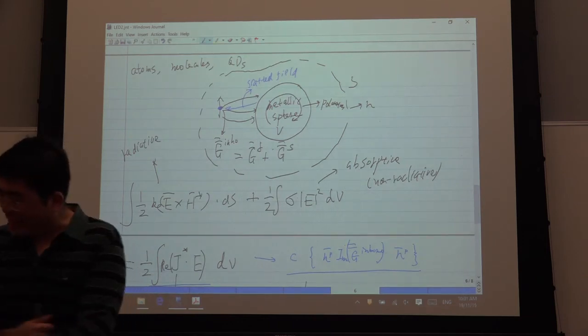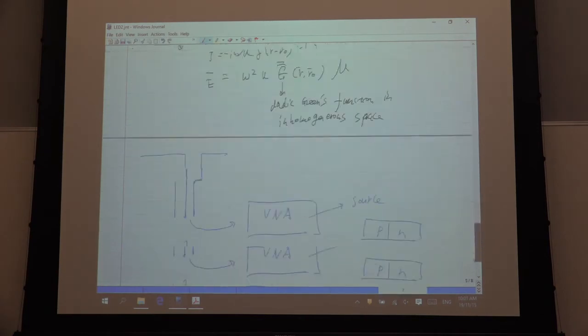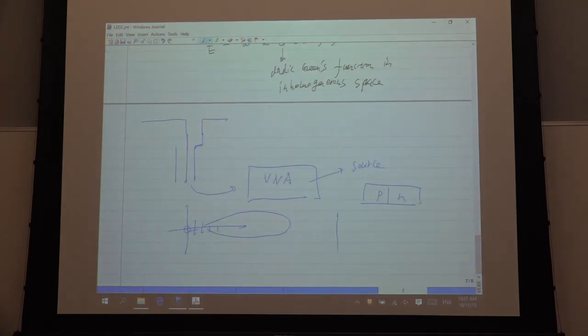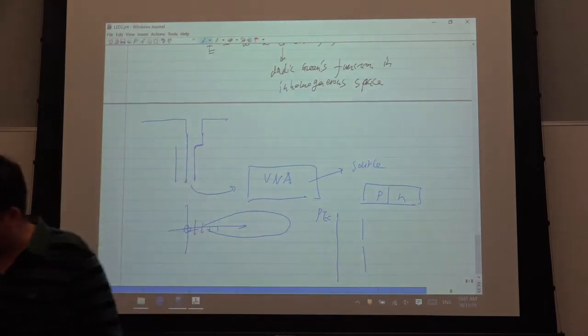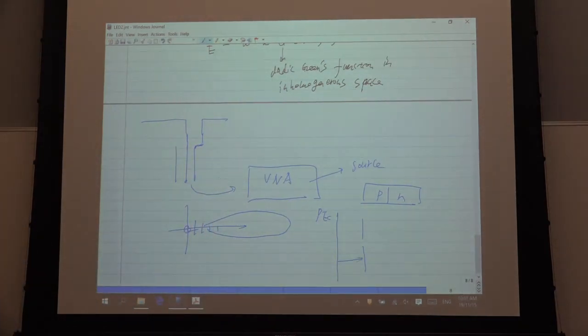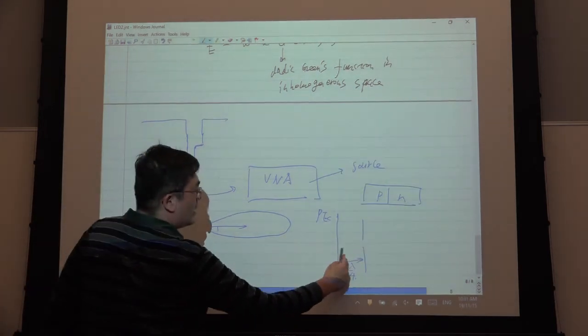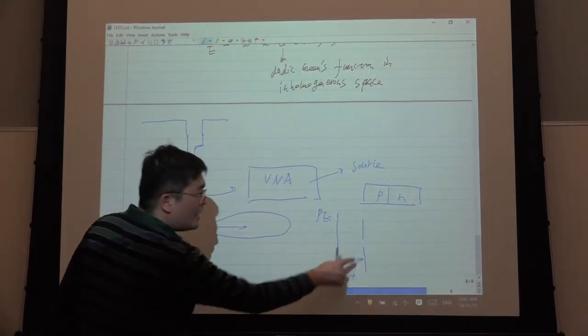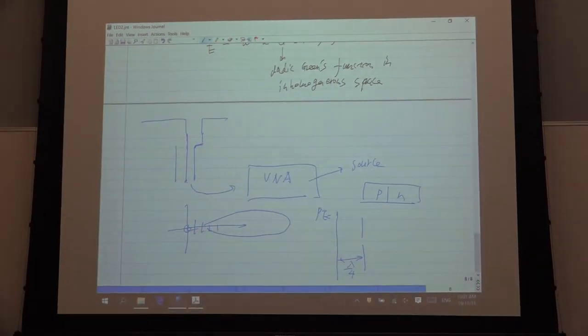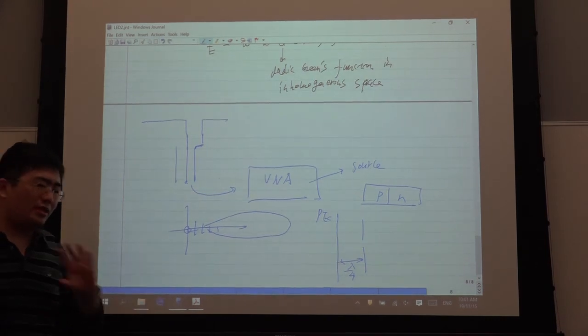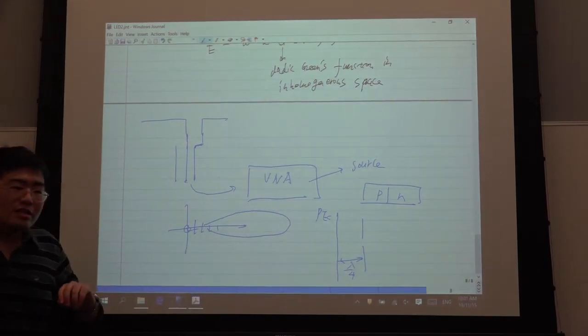This is quite different. I'll give you an example. If I use a PEC, I put a dipole here. This dipole is a classical dipole. I assume this distance is lambda over 4, so from here they're in phase. They can increase the E field at this point, but they do not increase the radiation power. They just change the directivity. But that is okay.